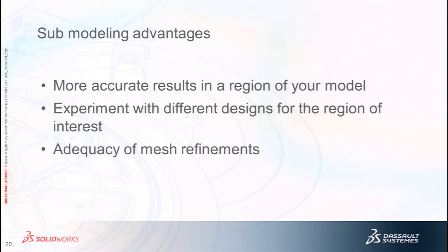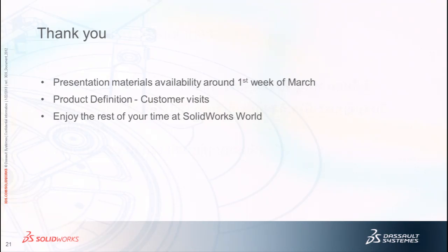So just to wrap up, there are some advantages of using submodeling. You can try to get more accurate results at the area of interest. You can experiment with different designs, and also make sure your mesh refinements are enough to get accurate results.